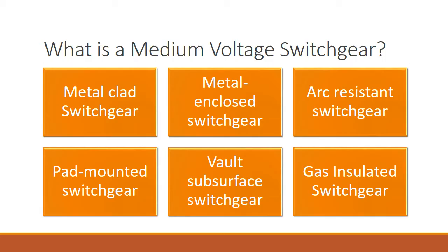Now, when compared to equivalent air-insulated switchgear, the use of gas as an insulating medium allows for shorter distance between interrupting components. Now, the ANSI IEEE standards C37.60 and C37.72 are used to design and test these gas-insulated switchgear. The gas-insulated switchgear was developed, built, and tested to the International Electrotechnical Commission performance standard, IEC 62271, prior to the IEEE C37.20.9 for the GIS switchgear.